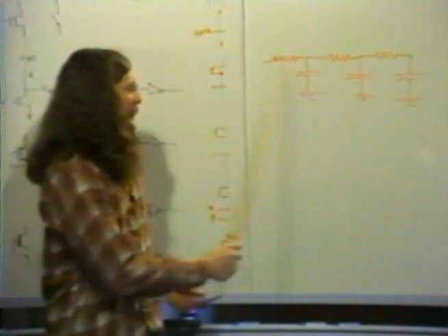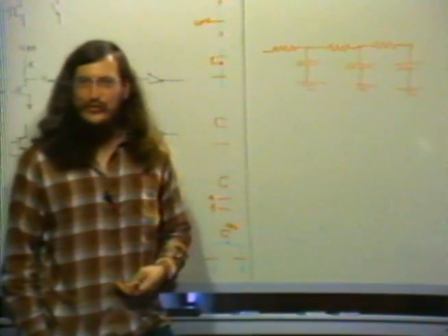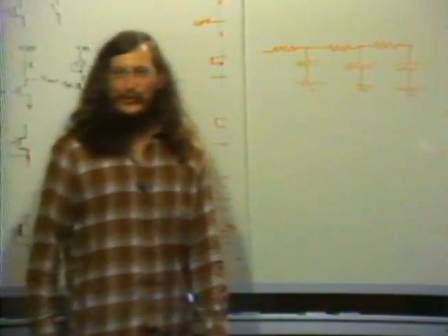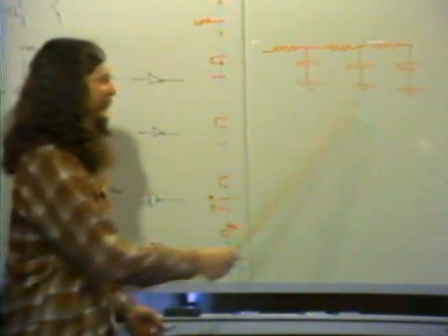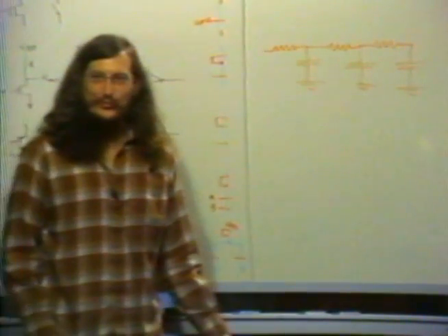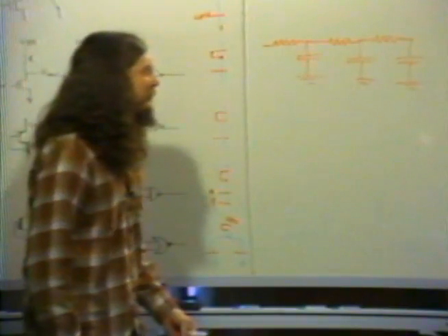And in fact, if you make your wire twice as long, once it's in the regime of being limited by diffusion time, the diffusion time will in fact be 4 times as long. So the time delay is like the square of the wire length for long wires. Fortunately, it's negligible for most wires, but you'll see it's not always negligible.